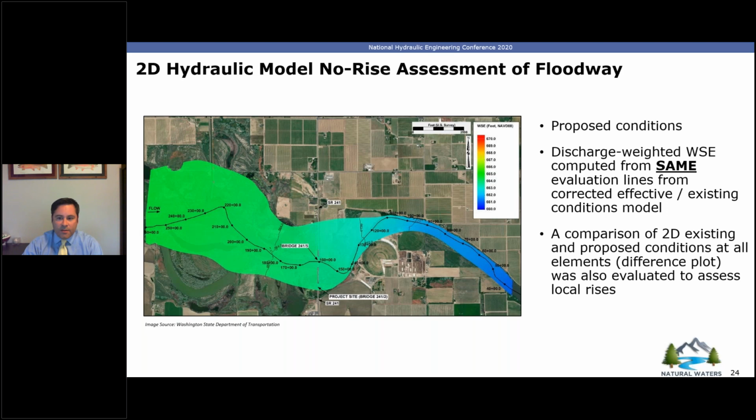Yes, a variety of sensitivity analyses should be undertaken to see how the model results would change if you were to change that given attribute. So in this case, to answer that question specifically for the mesh, there was a sensitivity analysis conducted on mesh size to make sure that there was no change in hydraulic model results.